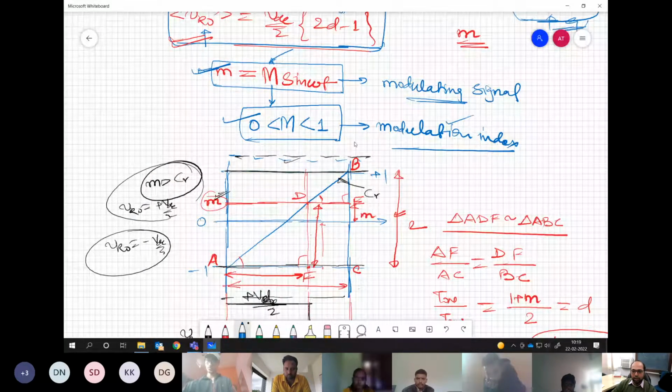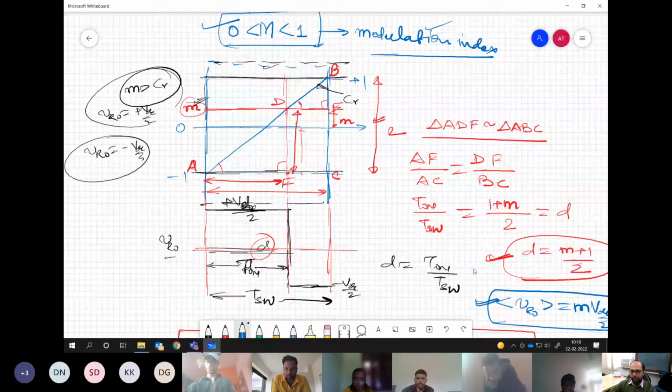Now this is different from what we have seen in the low switching frequency case because we have a different PWM. Then we derived and found that the average pole voltage per switching cycle, or per half switching cycle, is related like this. What is true for half switching cycle is also true for the full switching cycle and hence for the entire waveform.